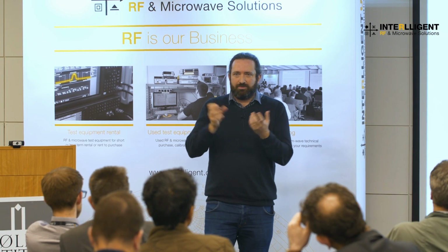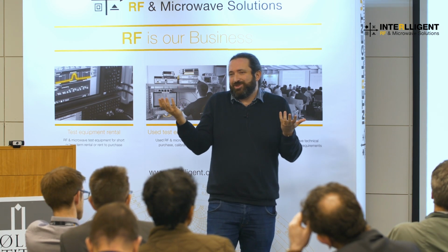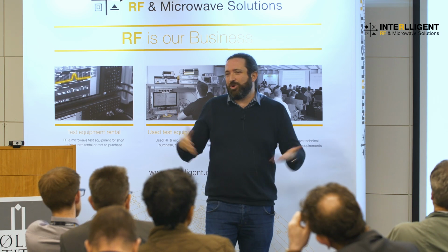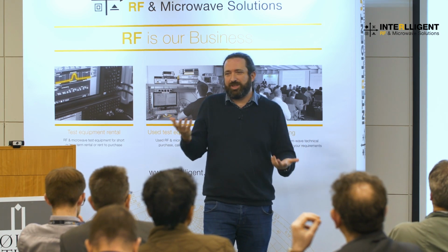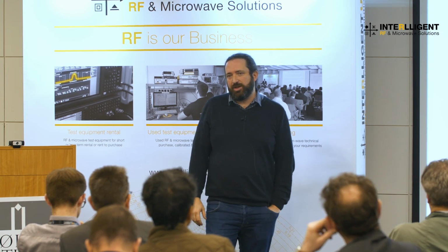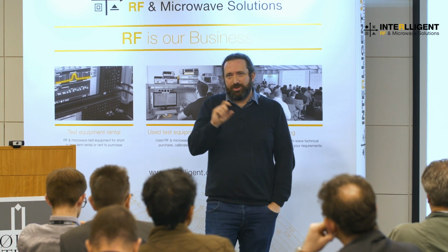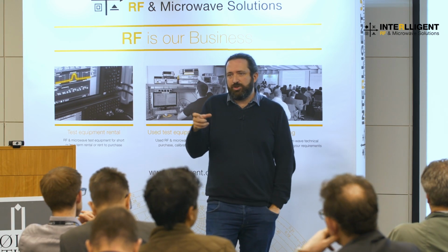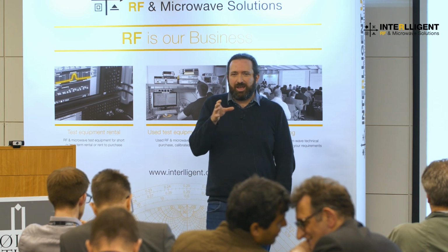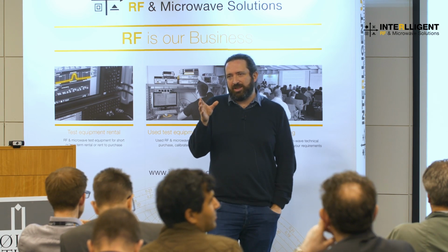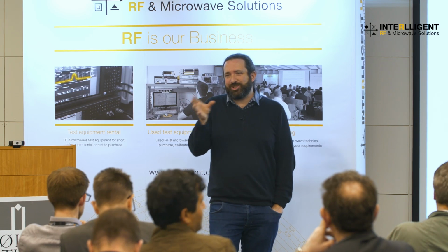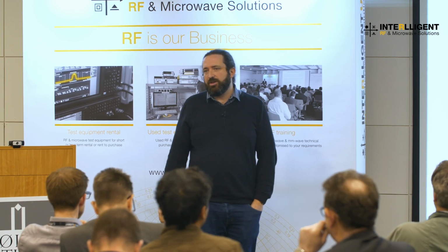So you're right, you cannot expect them to be accurate, because they are general, broadband models and they cover S parameters. So it's just not an expectation. I think it's also about trying to leverage the measurements you do and understand, oh, maybe I'm losing a bit more power than I expected. I increase the periphery a bit, but then of course there's capacitance I need to account for, so things like that.